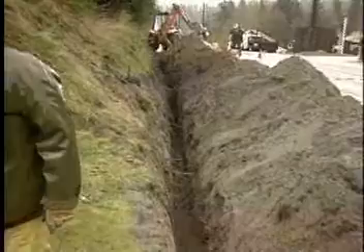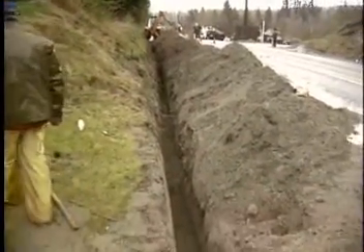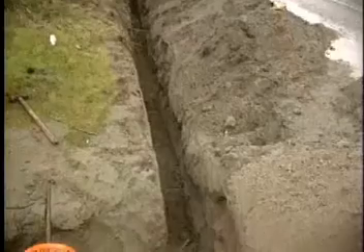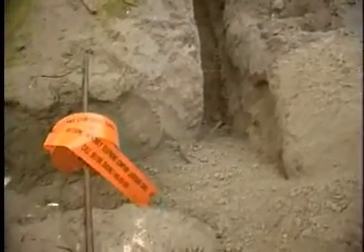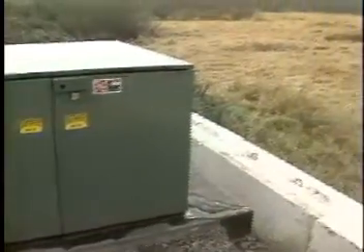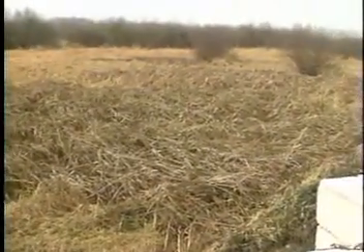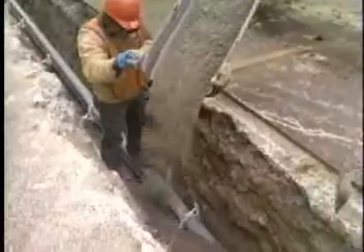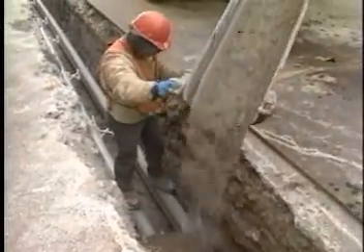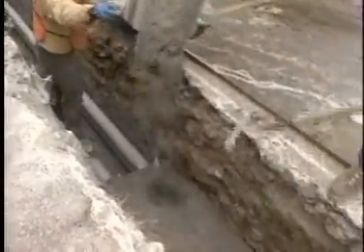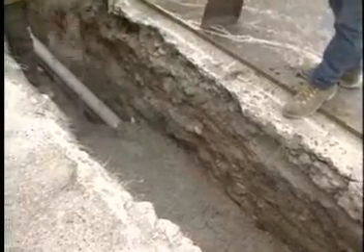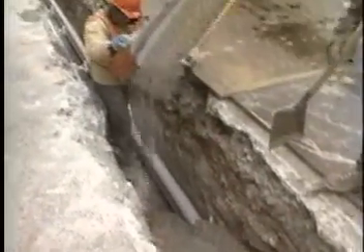At the bottom of the trench, a 7.5 centimeter depth of fine sand or dirt should be placed prior to laying the conduit, duct, or cable. In marshy or unstable areas, a 7.5 centimeter slab of concrete can be poured to provide a stable base. In urban areas, or wherever added protection is needed from dig-up or crush forces, concrete can be poured over the duct structure as well.